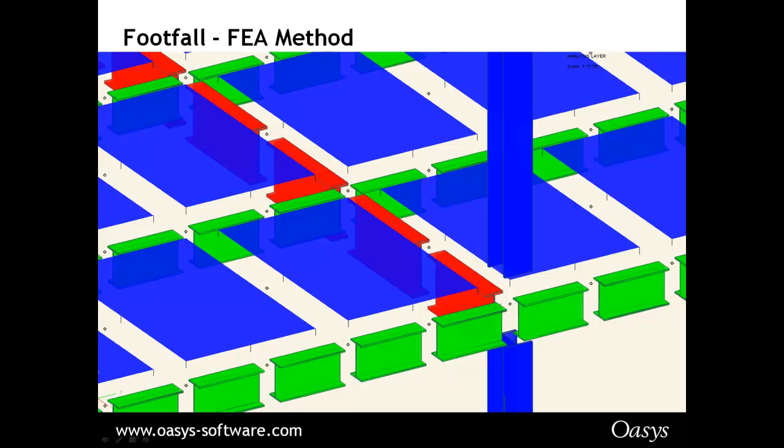Obviously you pin it in the vertical direction, but pinning it in the horizontal direction also has the advantage that, because for footfall vibrations we are only interested in vertical movement on the floor, those horizontal restraints just prevent those horizontal modes of vibration. If you're doing whole building seismic, completely different case, obviously.